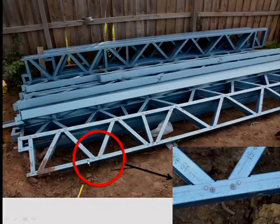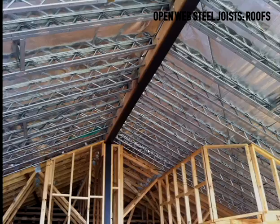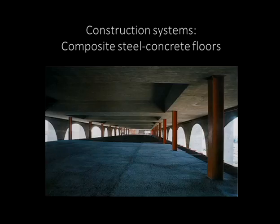Look at the connections here. So these are just screws for the bars of the truss. They are only subject to axial forces, so there is no bending in a truss system, remember that. The same system applies to roofs. And now I'd like to talk a little bit about Bondek.